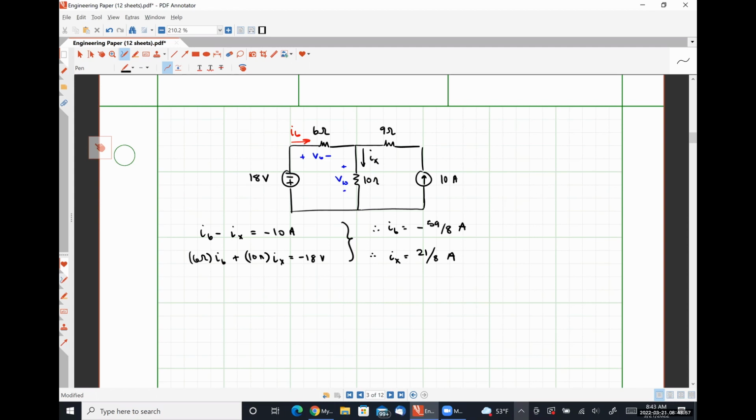that's really kind of an interesting thing about sources. Sources aren't inherently linear or nonlinear. They just depend on what they are connected to. Okay, so really, if the circuit contains resistors, capacitors, and inductors, as long as those are not time-varying quantities, then we have a linear circuit. And if we have something like a photoresistor whose resistance value depends on some external stimulation, that would be an example of a nonlinear circuit. Diodes and transistors are inherently nonlinear as well, which we're not going to talk about in this class at all.